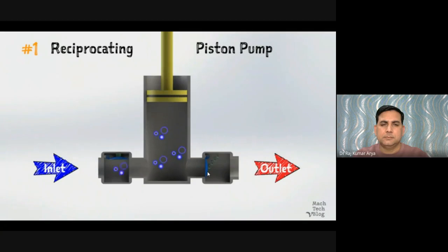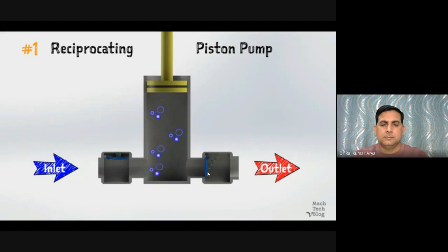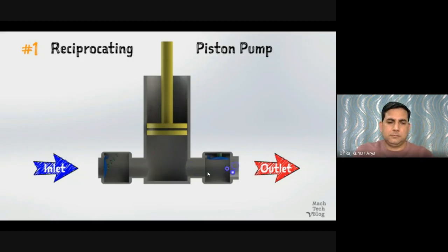By definition, check valves permit flow in one direction only, so they help to prevent backflow and direct the fluid through the pump. As the valve on the suction side of the pump opens, the valve on the discharge side closes. On the discharge stroke, which is the downstroke here, the piston pushes on the fluid in the cylinder. The pressure rises. The suction valve now closes, and the discharge valve opens to release fluid into the system.